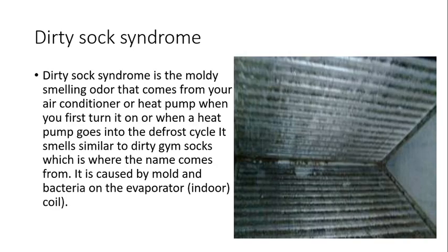Dirty sock syndrome. Dirty sock syndrome is just what it says. It's something that smells like dirty socks, and it's bacteria that builds up between the fine little gaps in the fins of the inside coil. It's almost the worst thing you want to have to deal with in a home, because getting it out is not easy. Sometimes you can spray stuff on it and it's not really bad and you can get it out, but sometimes it's so bad that the coil has to be taken out and soaked in a chemical to get it all out. But it's curable. It just sometimes is kind of expensive to do.